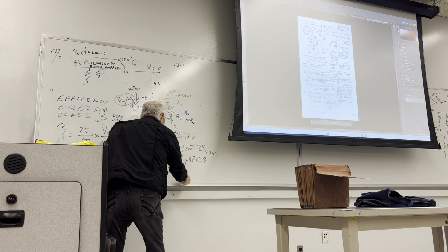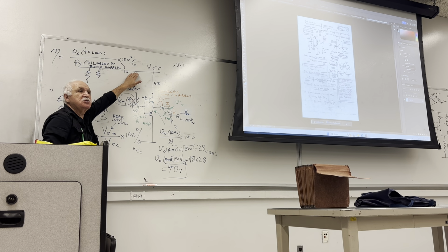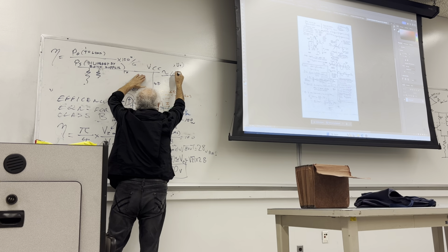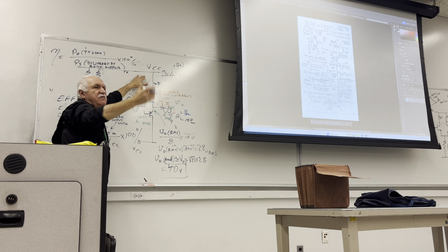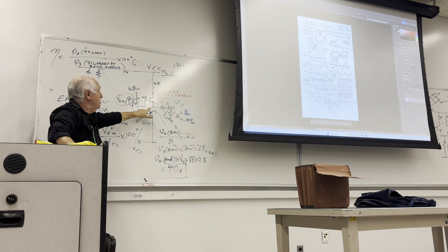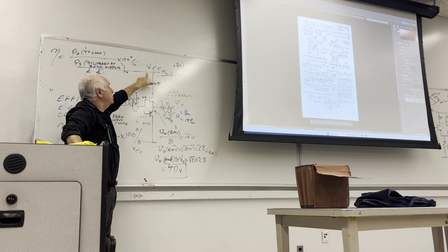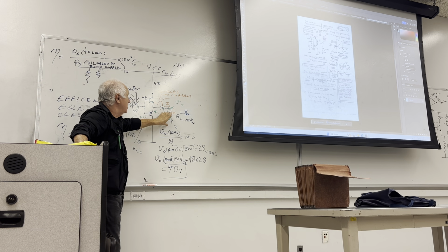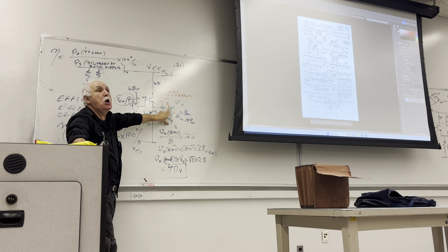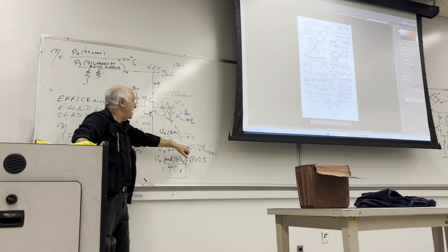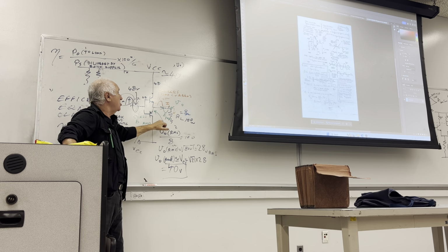So you need to set this power supply, gentlemen, to about 40 volt, or maybe 41 or 42 volts, so that the emitter can rise to the vicinity of 40 volt, creating a peak sinusoidal voltage across the load, that sinusoidal voltage can reach 28 volt of RMS,